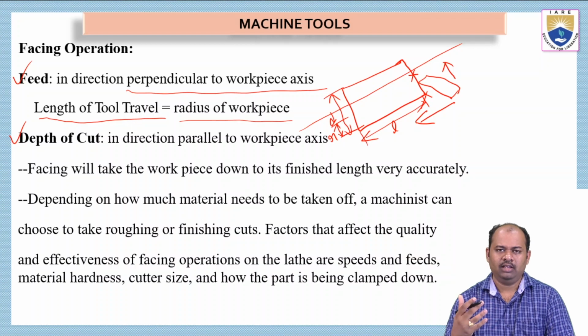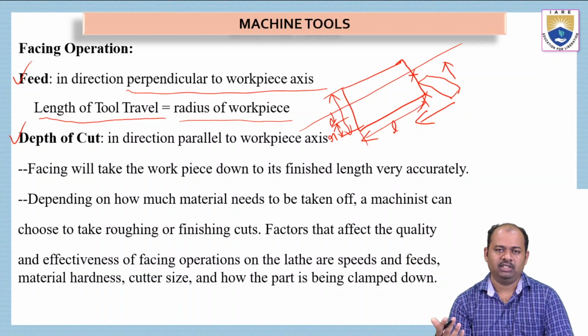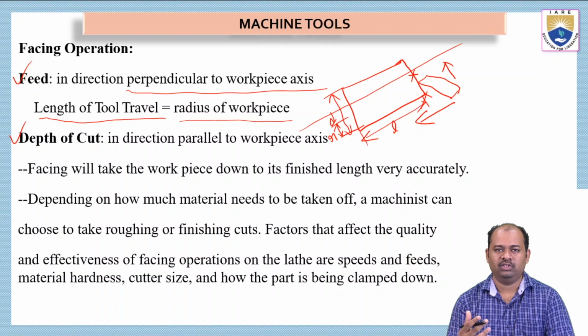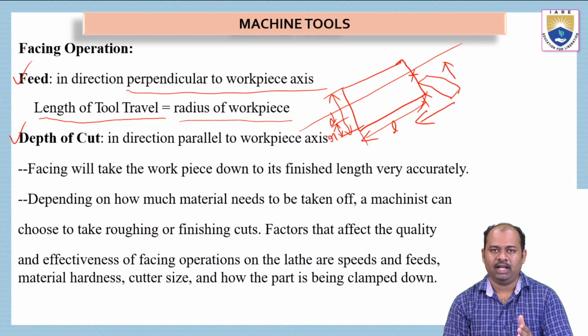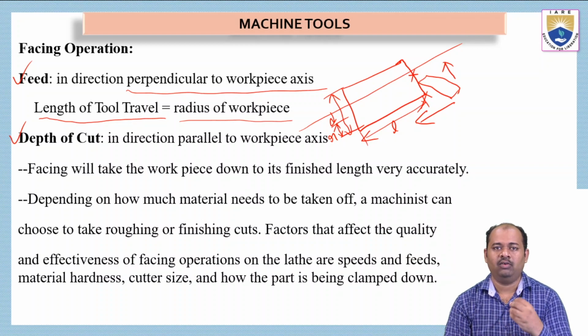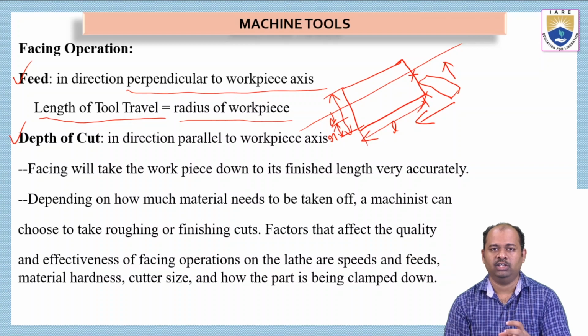Okay, we have other operations which can make the surface smooth, like grinding or honing operations, etc. They are used for making the surface smooth. So before going to that, if we want to remove only a smaller amount of material, we have to do this machining process very slowly so that we will get a smooth surface finish.